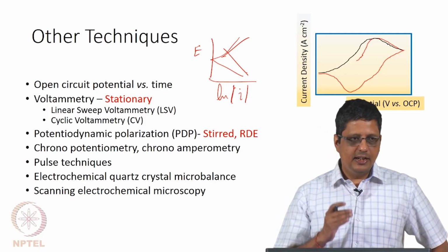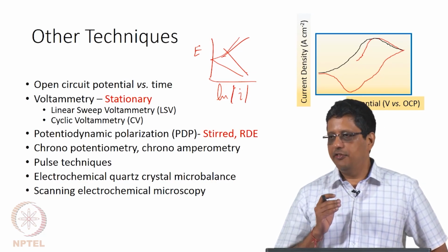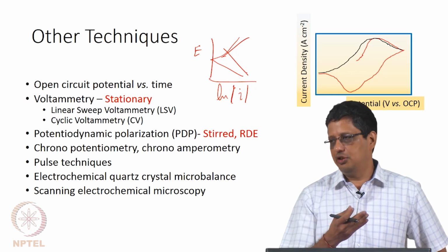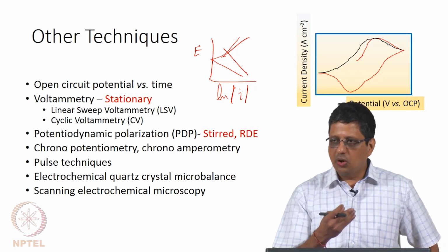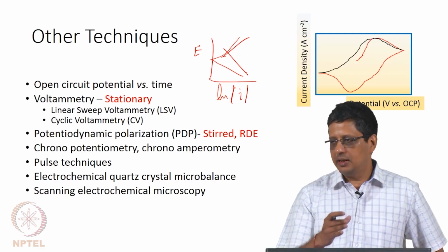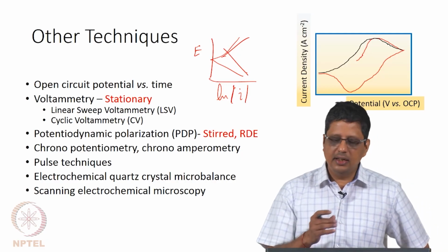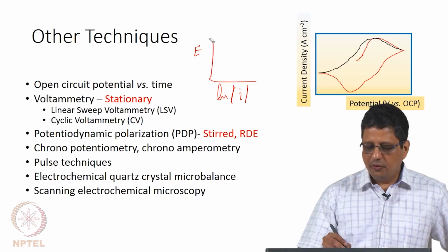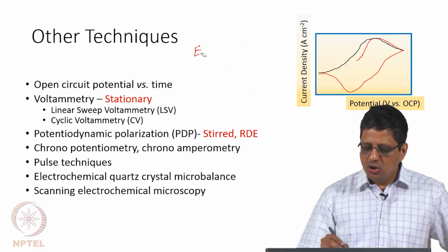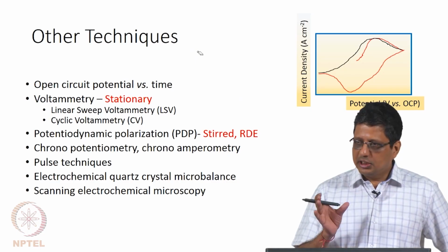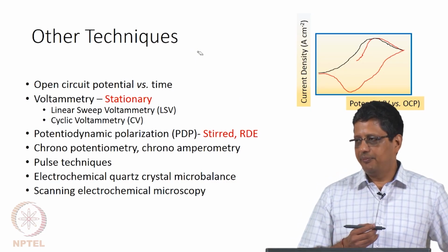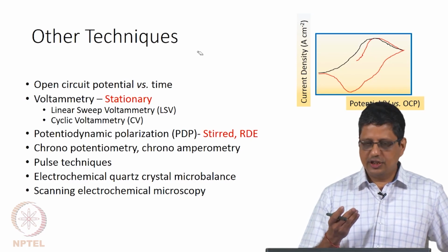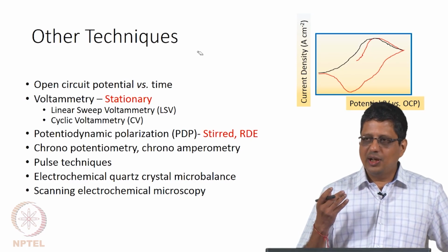If you have a significant corrosion current, a large current from the reaction, which means very fast dissolution, then you might be able to go at a slightly faster rate and still get the correct results, because the double layer capacitance will still not contribute that much current to the final value. So, we have for example done experiments at 2 millivolts per second, that is going to shorten the experimental time by half.